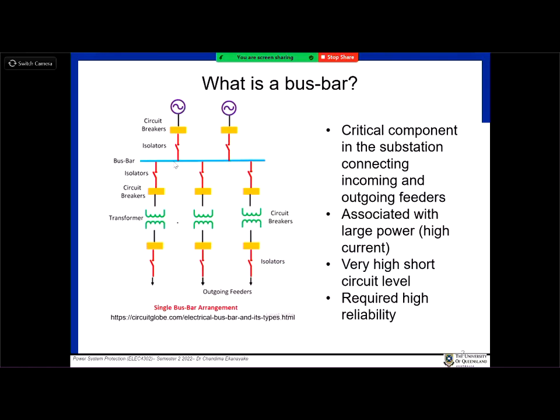In reality there will be some low voltage bus sector and then the high voltage bus. The incoming feeders and the supply to the substation are at two different voltage levels. This is a very generic model, but in a high voltage substation, the incoming feeders are connected to one bus and the outgoing ones to another bus, with a transformer between the two buses to reduce the voltage level.